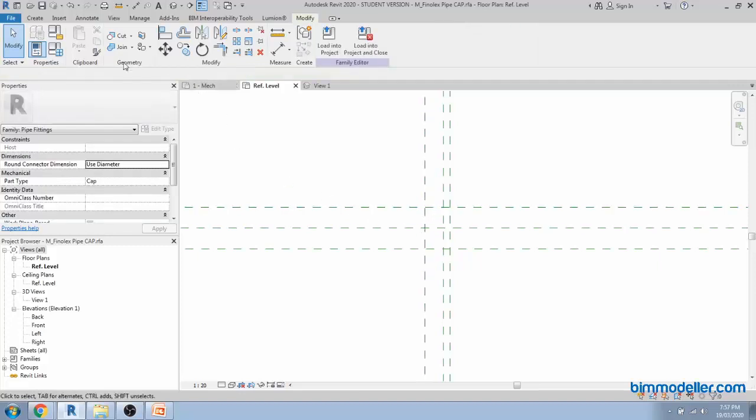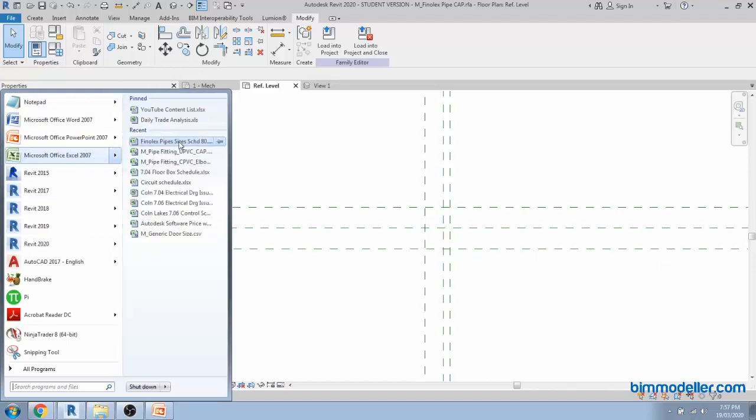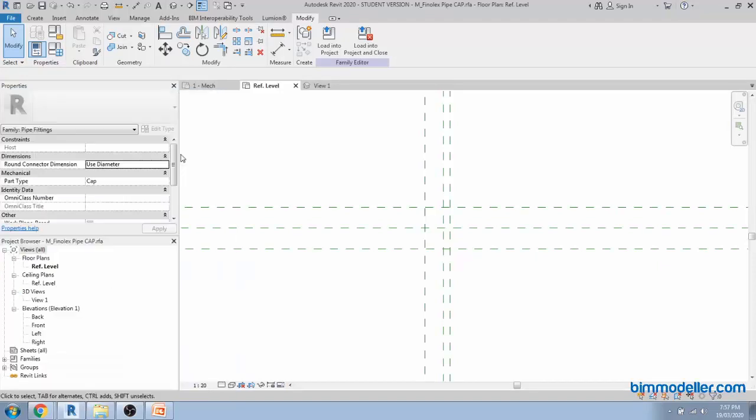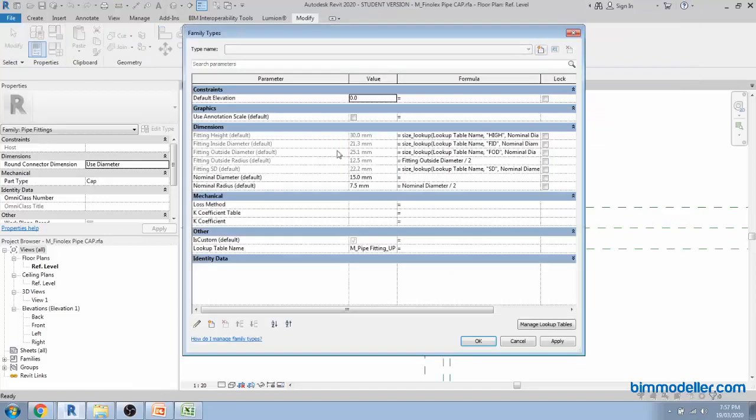So everything looks good, and if you try to create, for example, schedule final, let's use the cap, and if I try to assign the second value 20 or 25, what happens? We have to check. If I change that to 20, the values are changing. So if I say the value will be randomly 43, automatically the second value will be taken from the lookup table. If you're not familiar with how the lookup table formulas work, you can go back to the previous video.